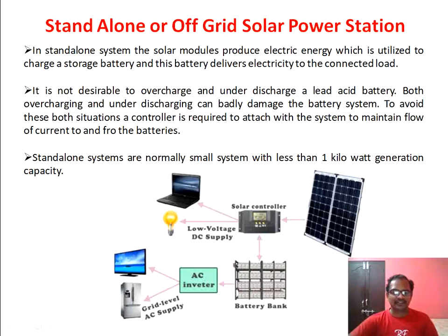This MPPT charge controller is a device which we have already seen. It performs many things. The first thing it will do is it will not overcharge the batteries, or undercharge the batteries, and then it will connect the battery to the load. It will connect the PV source to the load, right? So these are all different purposes or functions of a charge controller.